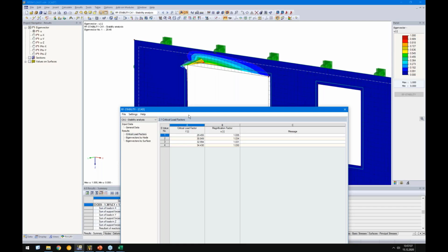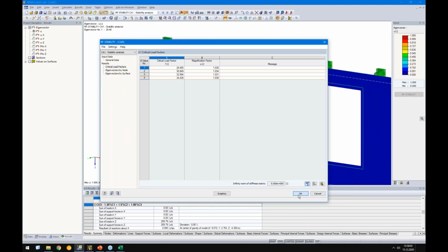So you need to analyze stability, because this is on the unsafe side, because no imperfections are considered and so on. But we have a good feeling with this factor, because it is common to use a factor from 1 to 10. We need to check stability, and everything that is bigger than 10, we can think about neglecting it, and in this case we definitely can neglect it.